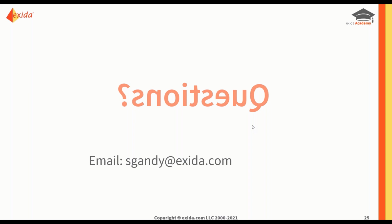Using a status signal output from the BPCS used by bypass or a startup override of a SIF, does prior use need to be performed on the BPCS controller? Oh dear. Well, normally the BPCS, to cover this, it's normally a 0.1 credit that's taken. So you can do a separate analysis if you think that you can do better than 0.1, but normally 0.1 would cover it.